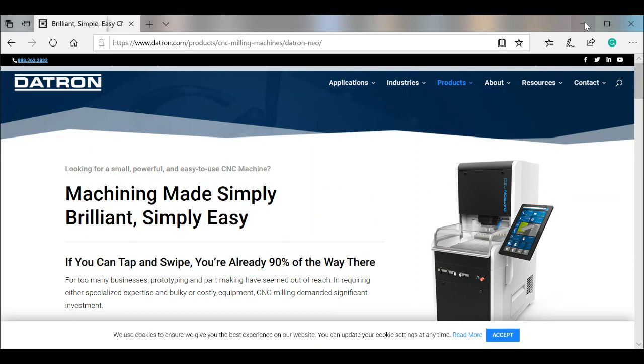Okay. Another question from Nelson. He wants to know how to build a via. You first build the holes with the laser engraver, then you print the silver, or is it reverse? No. First you drill the holes on your substrate, and then you print.